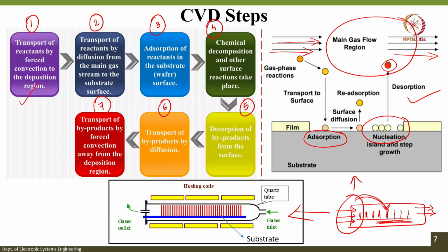And the figure below shows, just as a schematic, how a CVD reactor would look. You have a quartz tube that is shown in black color, where you have a substrate holder and all your substrates are arranged in a vertical direction. The number of substrates, that is, the number of wafers and how the wafers are stacked inside your chamber, everything depends upon the type of the CVD mechanism.